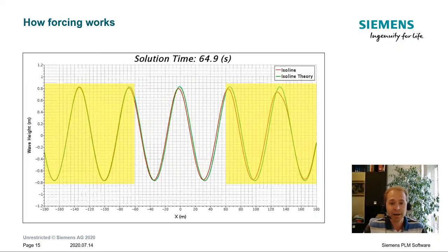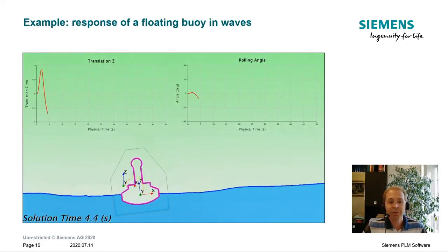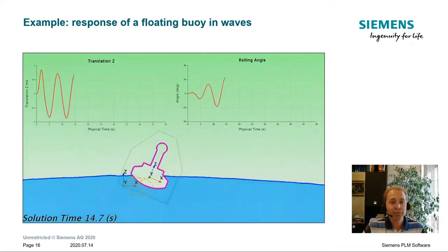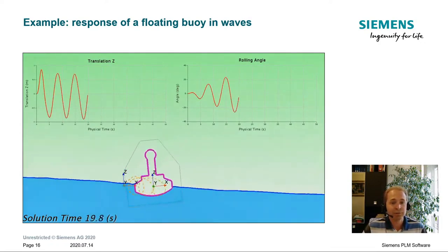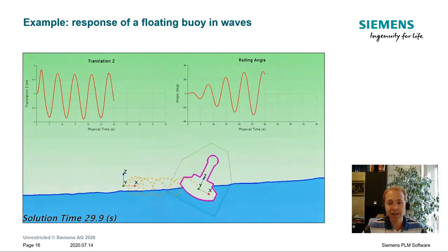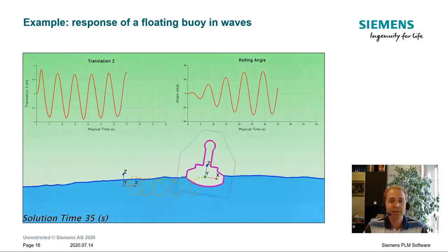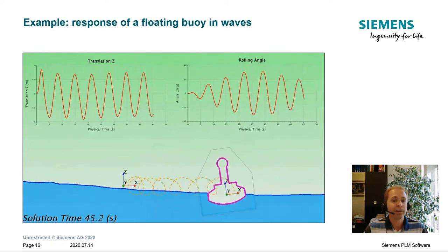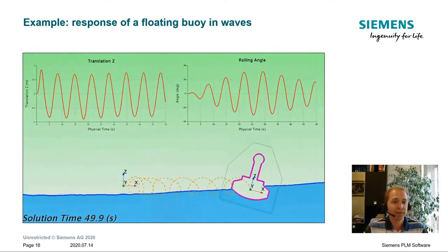and it is applied here both towards the outlet and at the inlet. Why? Well, to understand that, let's first put an object in waves, for example a buoy, and look at its response to the waves. Of course, thanks to the DFBI motion capabilities, we can follow the motion of the object and monitor all its behavior in terms of translation and associated Euler angles.